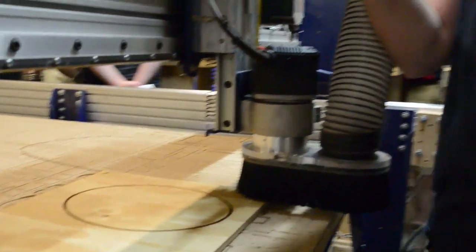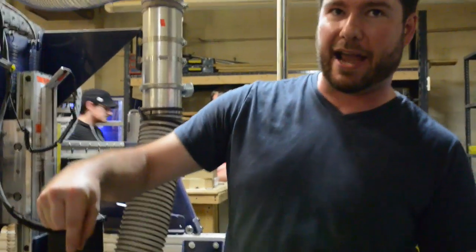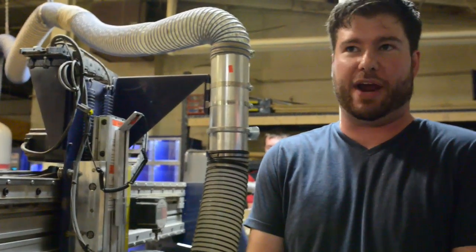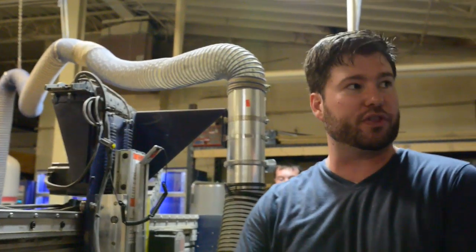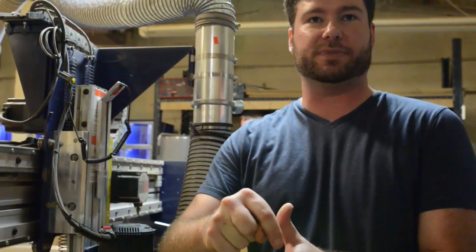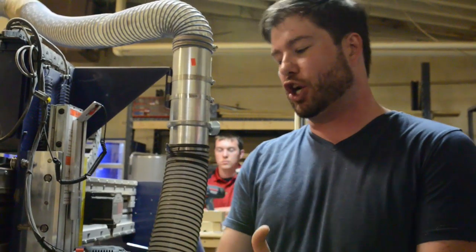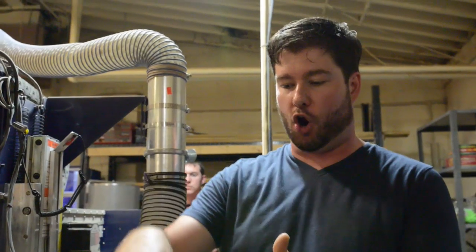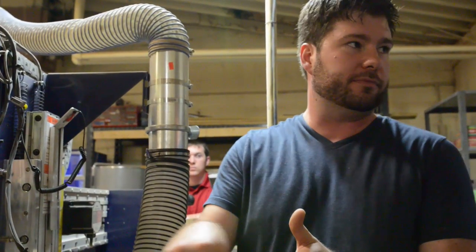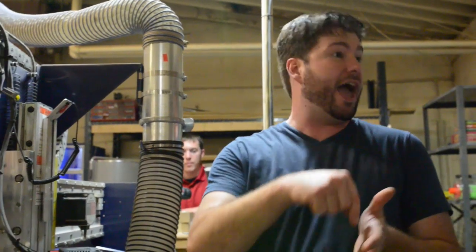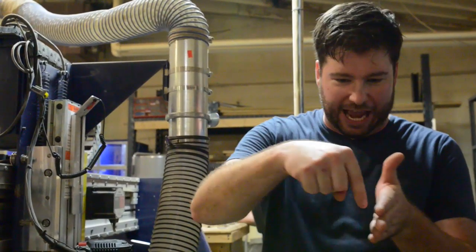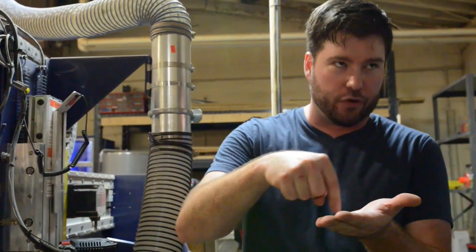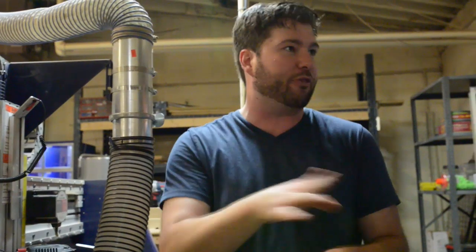And as you saw when it first came in and cut, it kind of zigzagged back a little bit. That's because of the ramp. Remember, it was a 3-inch ramp, so it had to do that little bit over 3 inches. That's all that was. It just helped save the life of my bit and created a cleaner cut. If I didn't have that ramp, it would have come over and started straight from there. But the ramp goes on the line. Even if it was a tiny little circle, if I had a 3-inch ramp, it would have gone around that circle exactly on the line, slowly, until it got through the ramp.